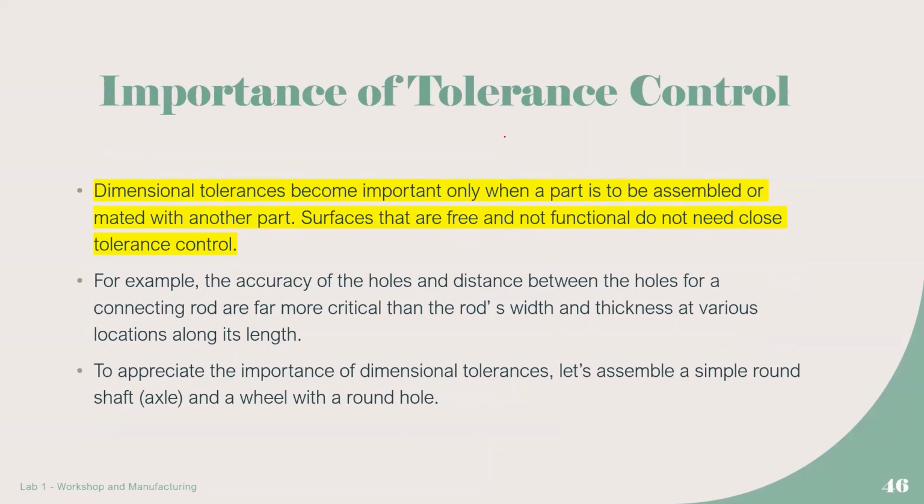The importance of tolerance control. Dimensional tolerances become important only when a part is to be assembled or mated with another part. Surfaces that are free and not functional do not need close tolerance control. For example, the accuracy of the holes and distances between the holes for a connecting rod are far more critical than the rod's width and thickness at various locations along its length.